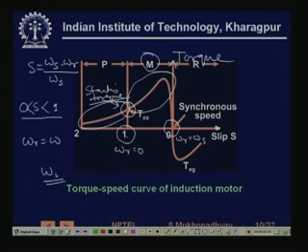So omega r will still be rotating in the same direction for some time, but omega s you can electronically reverse its direction, in which case you will be operating in this zone. There will be a very large current flowing, because now the relative rate of change of induced EMF is very high, and so high current will flow and a lot of heat will be dissipated.